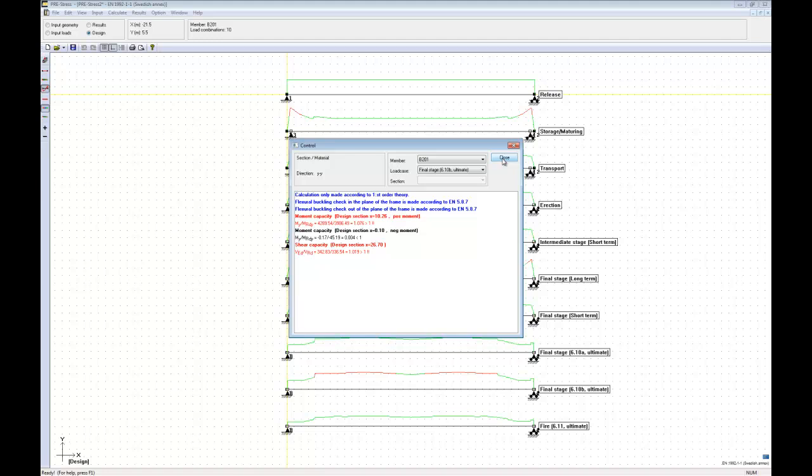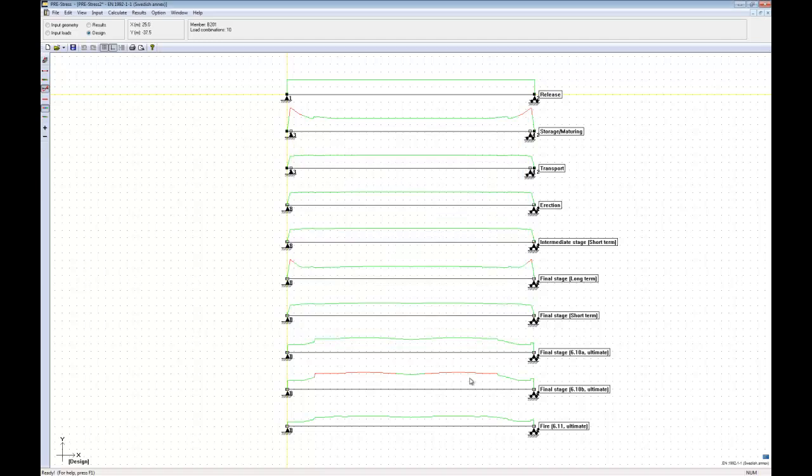What you can do to solve both these problems is that you add a non-tensioned, let's say diameter 16 bar or 25 bar in the bottom, because then you will improve the load combination here and you will actually reduce the compression stress in the section in the early stages, because this very thick reinforcement bar will take the compressive stresses and help with that as well.